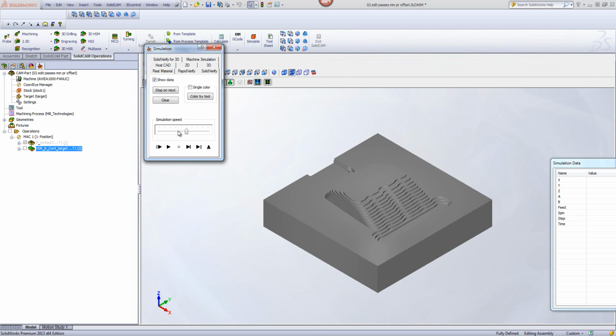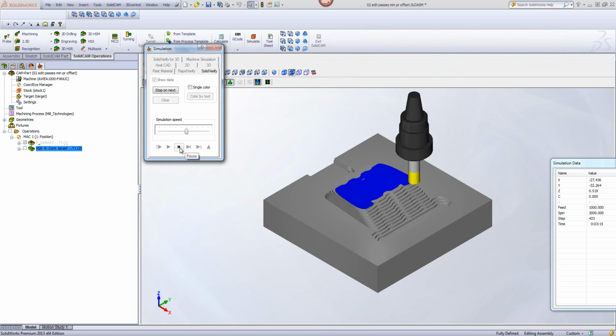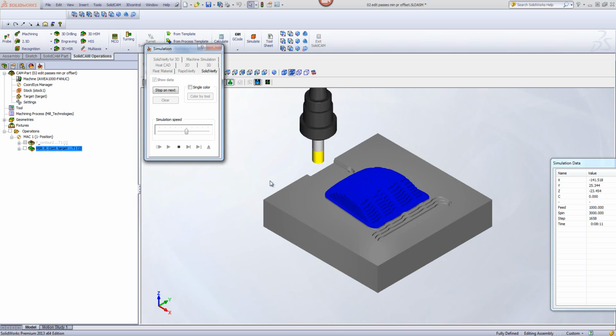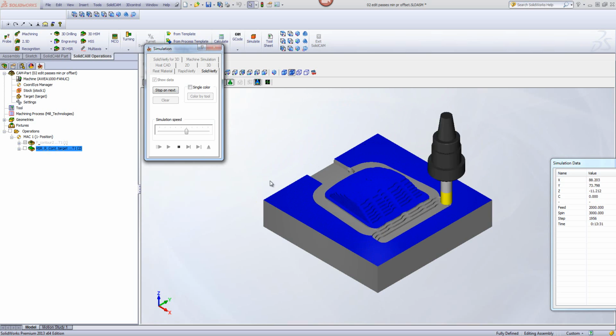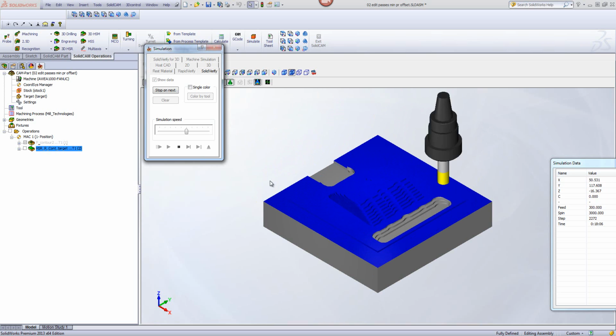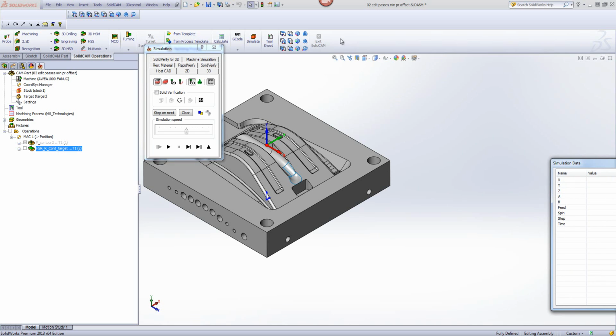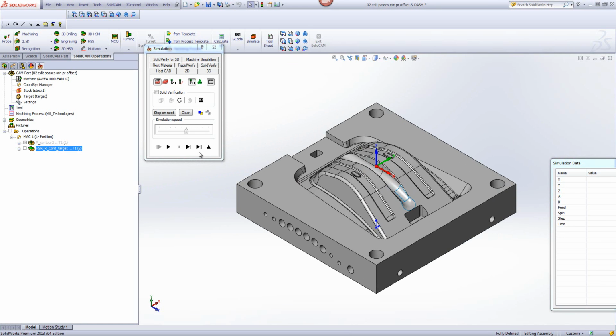And what you'll see is very simple. It's working only with this material, exactly 7 millimeters. Now, it didn't see the material because there was no material over here, really. I just brought this in as my stock. But all I did was tell it that it was 7 millimeters larger on all sides, and it machines exactly in those areas. Let me just run the simulation one more time, this time using the host CAD so you can see where the tool passes exactly are.